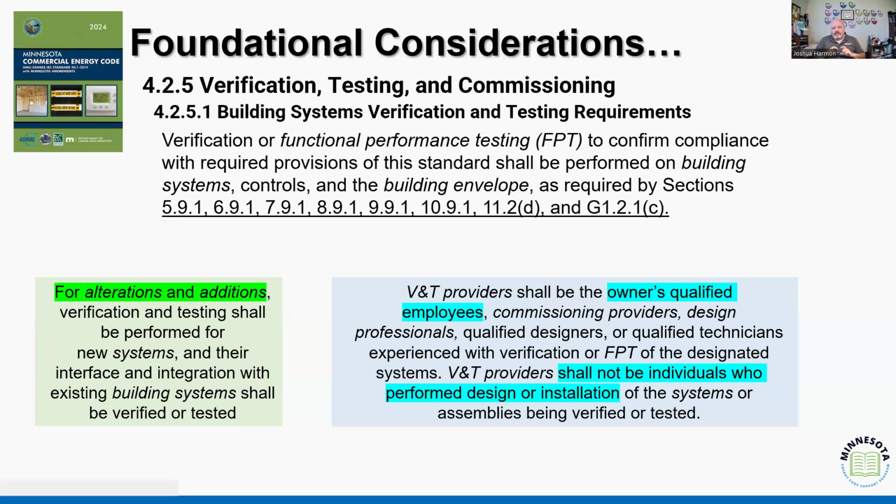It's that verification provider that's going to be the one who's on site. We think about this like special inspections, right? If we're doing some kind of structural steel or maybe some special concrete, we may be using special inspectors to provide a more thorough, continuous type of inspection. That's what I think, in my mind, most closely aligns to the expectation we see here.